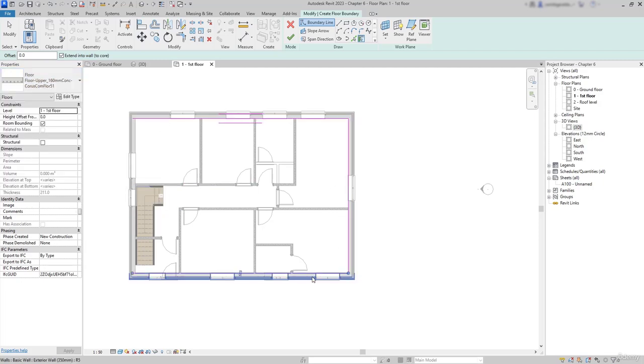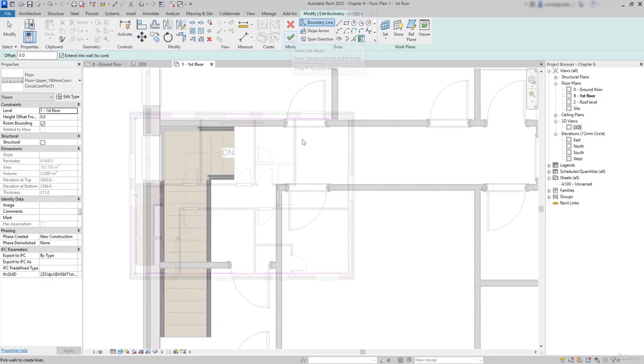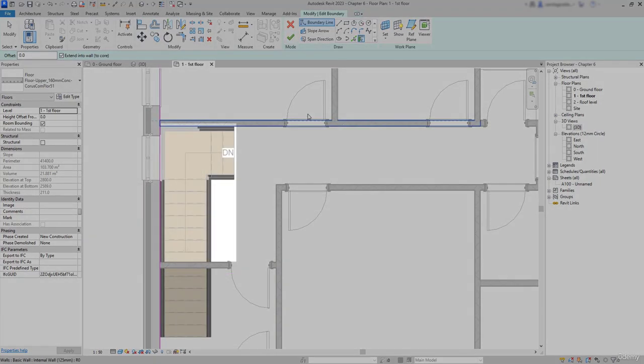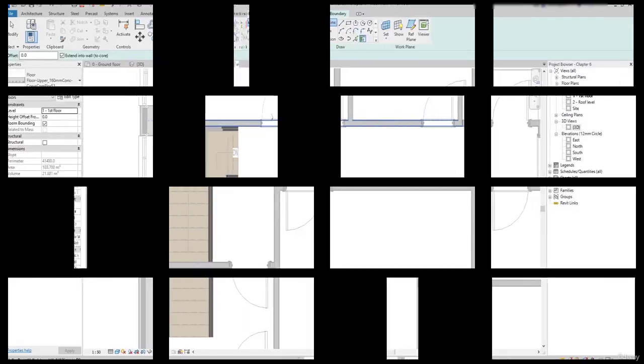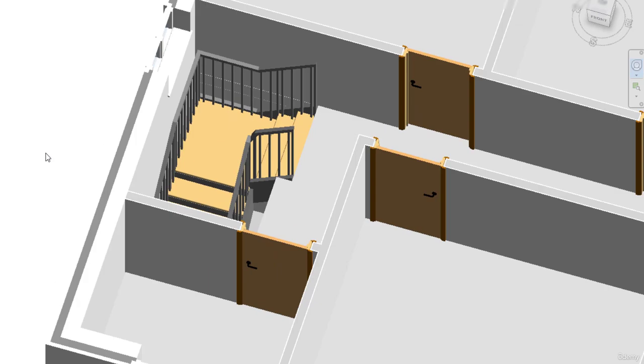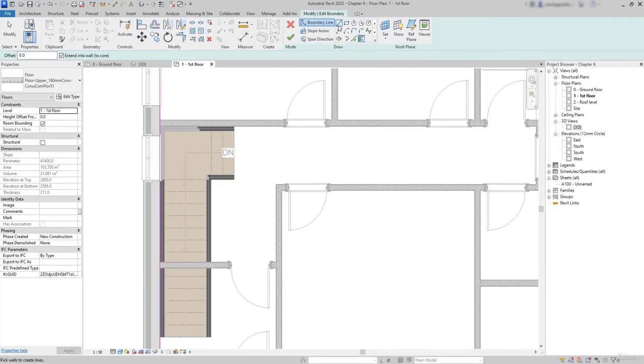In the same way as the floor below, I'm starting with picking walls, and then I need an empty area without floor here around the stairs, in order that people can reach the first floor, of course. The method I'm choosing is, I'm switching here to draw a line, then I go to this intersection and draw an area with lines here. Then everything can be edited later if we need.